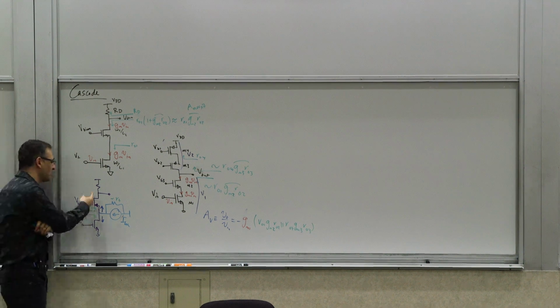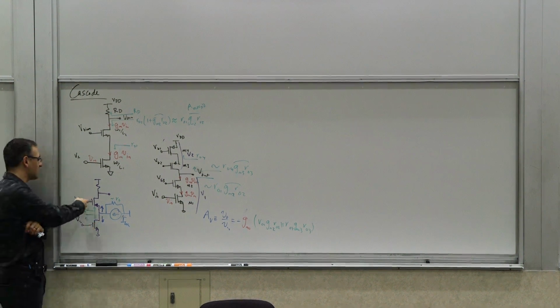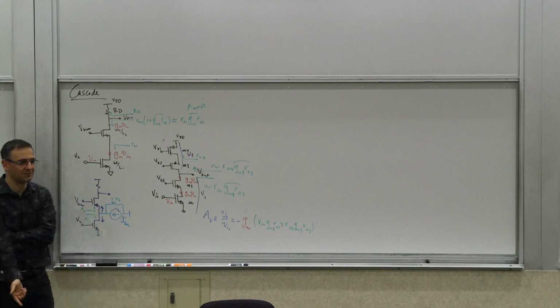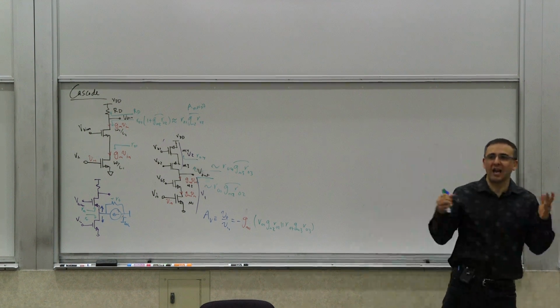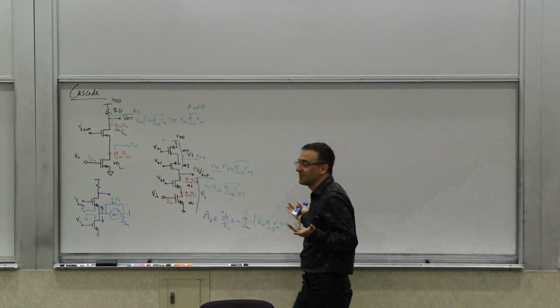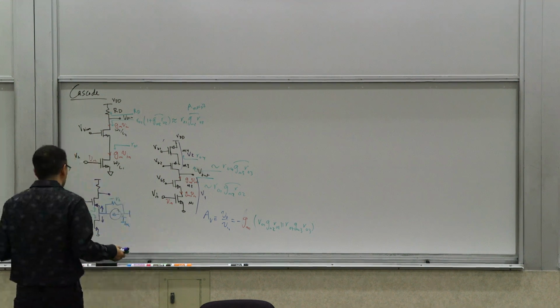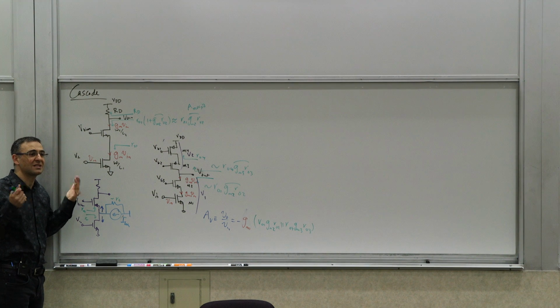So it's a fluctuation of this current anyway, so we can model it the same way. The small signal model for this thing is exactly the same as that of the NMOS, which is very convenient. So your small signal model remains the same for PNP or NPN, NFET and PFET, or N-type and P-type devices. Doesn't matter. The small signal model is the same, because it's an incremental model.